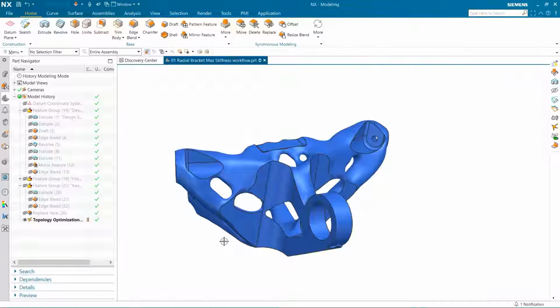I then added symmetry to the part and made a minimum thickness. You saw me pin the bolt holes and add a force and torque to the larger hole. You then saw me inspect the results and then create a clone study with 3D printing in mind.